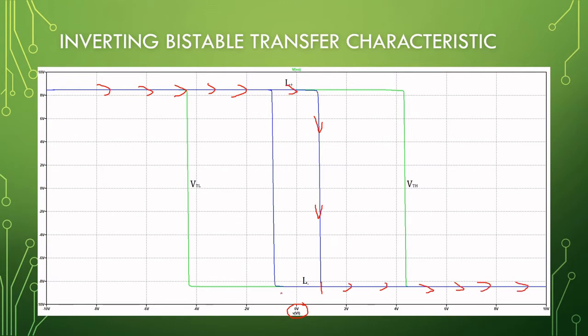So the moment that the input reaches minus 1 volt, our output will change back to the positive limit. The trigger level is dependent on the amplifier output, giving us this hysteresis loop.